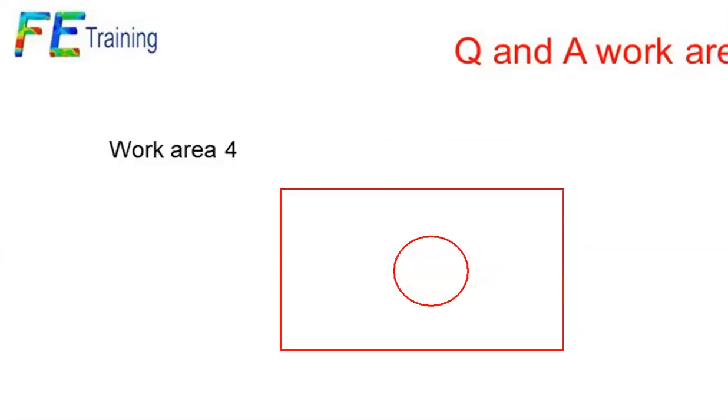In general, I'm thinking I've got a maximum principal stress. I align that with a fatigue crack and assume the crack is normal to that. I can't get any worse than that. Maybe my maximum principal is actually at a slight angle off that. So we swing. Have I drawn that the right way around? I've got a crack going. Yeah, that's the right way around. So maybe the maximum principal is over here. I'd swing that around. This is for uniaxial.